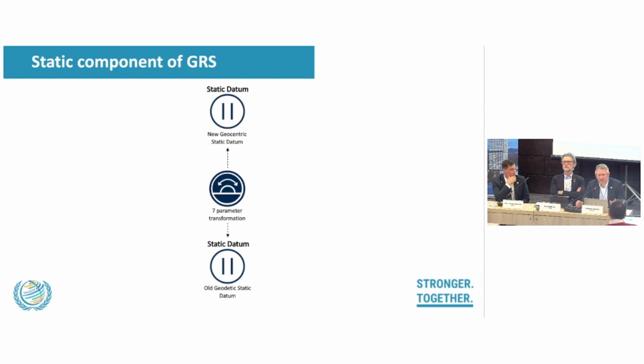Okay, so the example in Europe I can understand, but that's very different to some of the other countries, because in Europe you're already using a datum which is linked with ITRF. So it's within centimeters to decimeters of what you're getting in real-time ITRF. No, our national system is on an old ellipsoid, and it's 100 meters off, which is actually quite convenient because if someone forgets to do the transformation, you immediately see it because all your coordinates are 100 meters to the north. So if I see a difference of 100 meters to the north, I immediately know what the problem is.